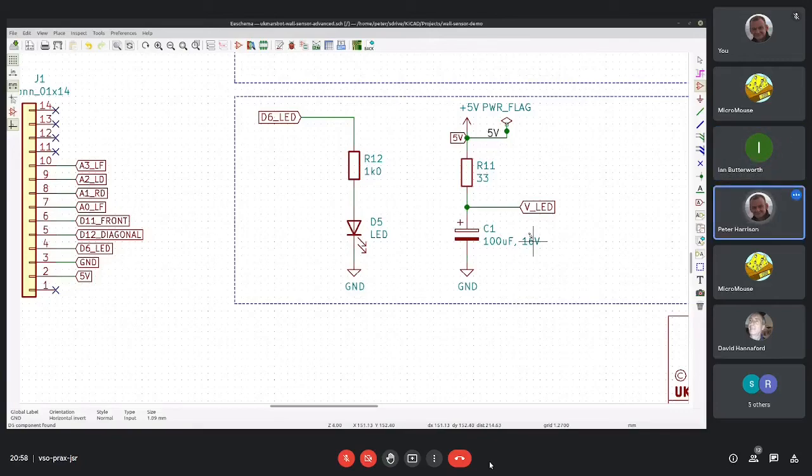I followed the rules. It's entirely possible. I just haven't tried it, so I don't know. I can't claim that I'm hugely experienced with KiCad, but I already know more about using it than I do about Eagle, possibly. I only did it because that's the way essentially the tutorial ran you through. Draw your schematics, choose your footprints, get everything labeled up, and then just go straight to board. You didn't need to do the intermediate step. I'll give it a go later.